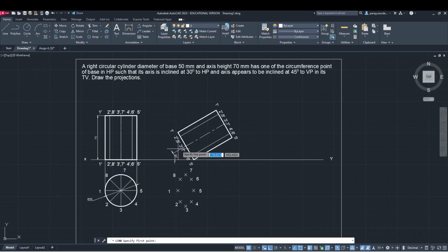we draw the projection for the center line for reference, just like this. And in this case, we also showed it this. Okay, so now we use the ellipse. Now in this case, we know the center. So let us select the center. We know in this case the axis endpoint. So we select this, and this is our other axis endpoint.